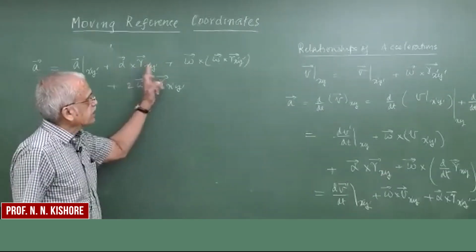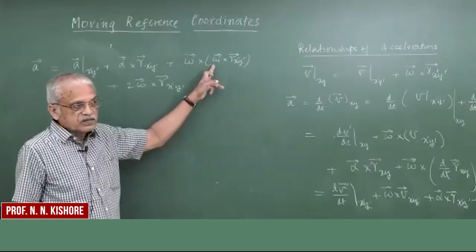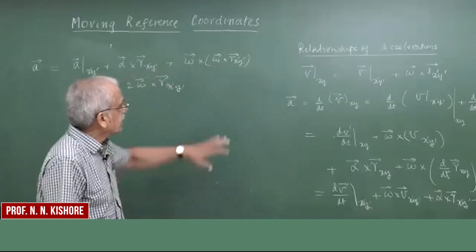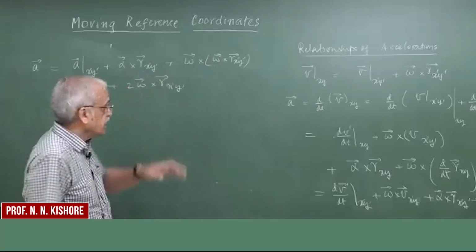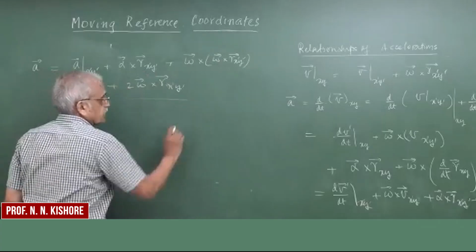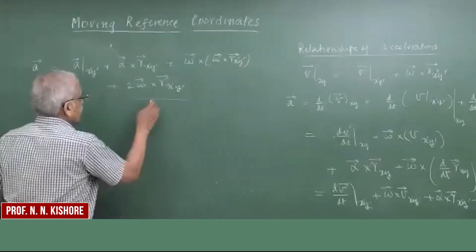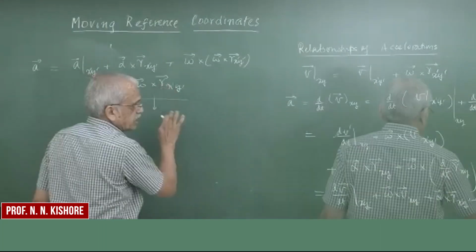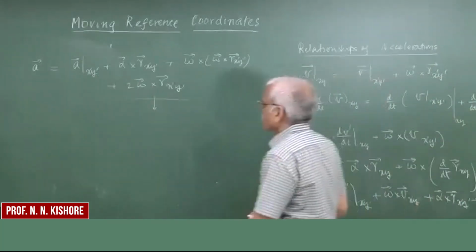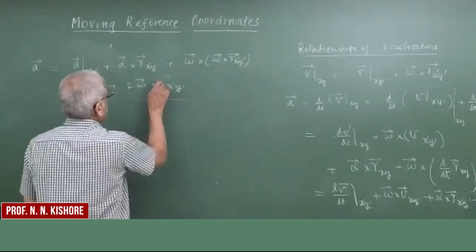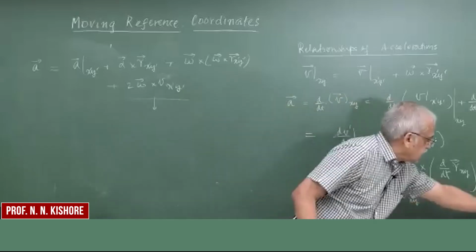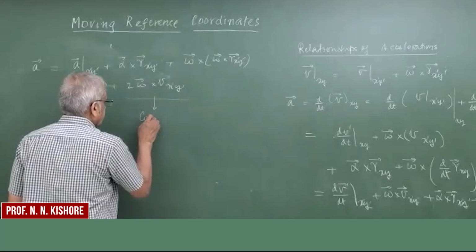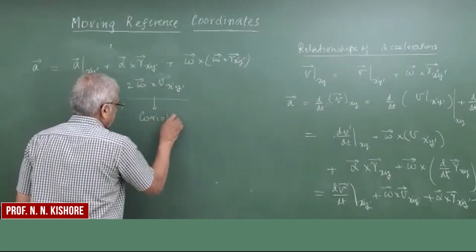r is the tangential acceleration. You can recognize what this term is. This is the centripetal acceleration, or normal acceleration, while the particle is moving in a circular motion. So this is the one which is usually not understandable: 2 omega cross, I'm sorry, this is V, Vxy, because this is d dt of rxy. This is the one which is known as the Coriolis term.